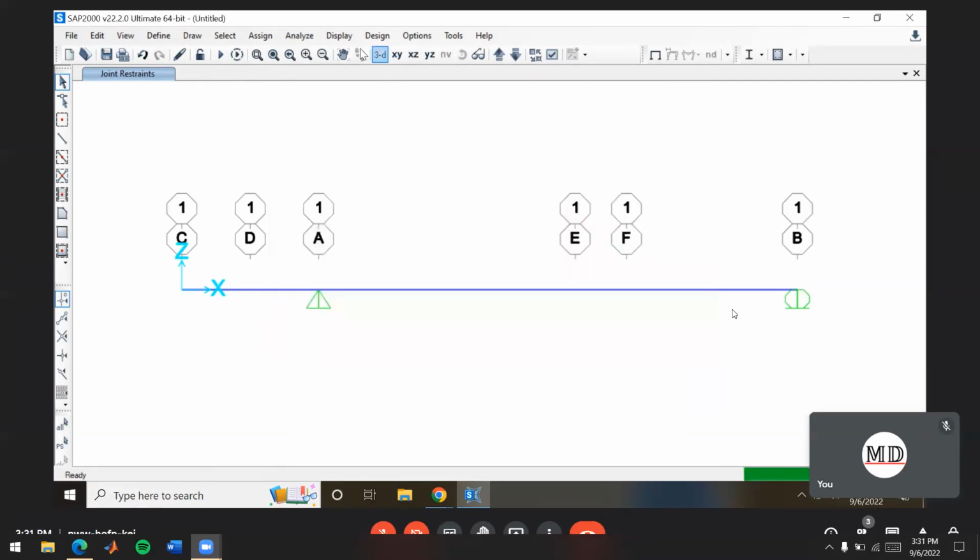Is one of these other ones? Nope. And then it shows us what all of our cross sections are assigned as right on the model there. Now, just like last week, if we don't want to be showing something, we can always get back to a default view of our model by pressing this Show Undeformed Shape button up here. That brings us back to a nice clean picture of the model without any of the annotation on top of it.